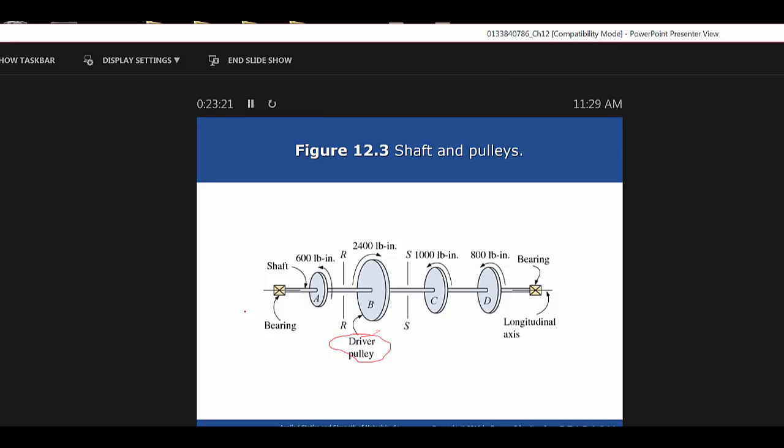If you total those up, they equal 2,400. So therefore, the entire system may be thought of as being in steady-state equilibrium. It's neither gaining nor losing speed. If the system as a whole is in equilibrium, every segment of the system must also be in equilibrium.